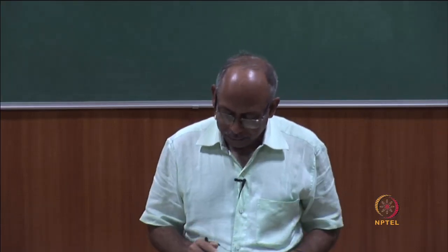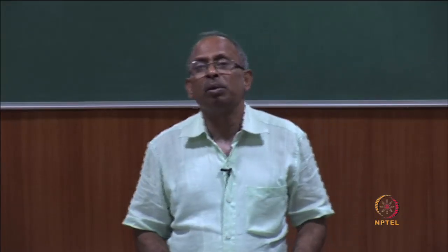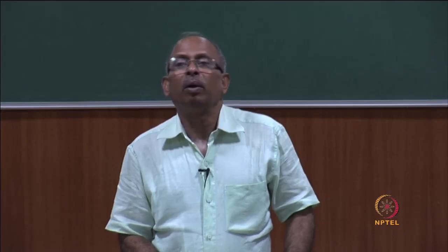So, this is time and relative humidity. If it is fully saturated, there could be swelling. If the relative humidity is very high, close to 100% or just 90% or so, shrinkage will be very little, but it is all related to drying.